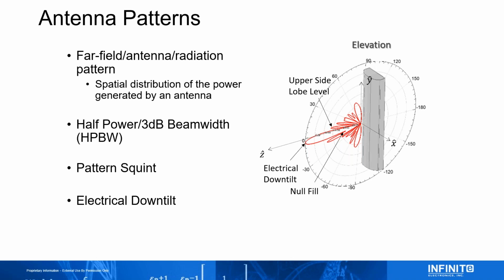And then another thing is the upper side lobe levels. You want to suppress these as much as you can, because these cause interference with, let's say, another tower that's 5 miles away. They're going to start talking due to this lobe right here. So if you suppress these down, less than 10, 15 dB, you usually can get away with any self-interference issue.